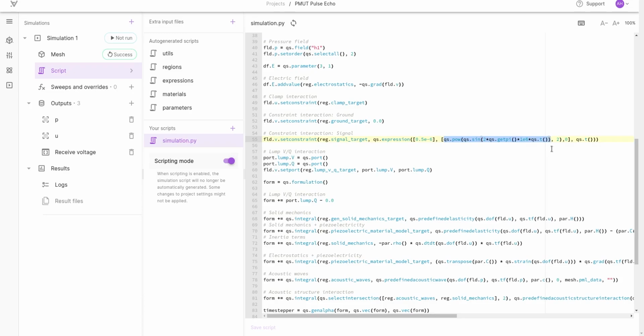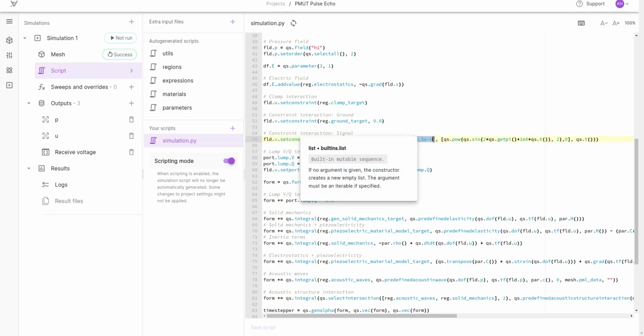And after half a microsecond, so basically half a period of the sine, then we will switch to the 0 expression. So basically we'll have a sine square volts, and when it comes back to 0, then we flatten out to 0. And the thing that decides in which of the parts of the piecewise defined expression we are is the time.